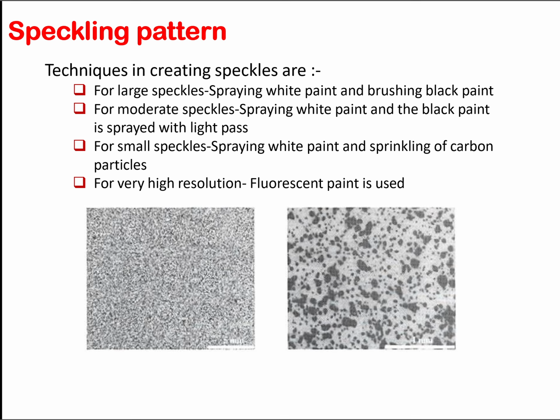And these are used for different types of analysis. We are going to focus on just a moderate speckle pattern in this lab. The idea is, again, you are going to take a picture of this specific instant in time where you apply a specific load, and then you are going to change the load. This point, for example, is going to move here, and you are going to track the movement. This movement tracking that is done for all of these speckles is going to help us calculate the strain.